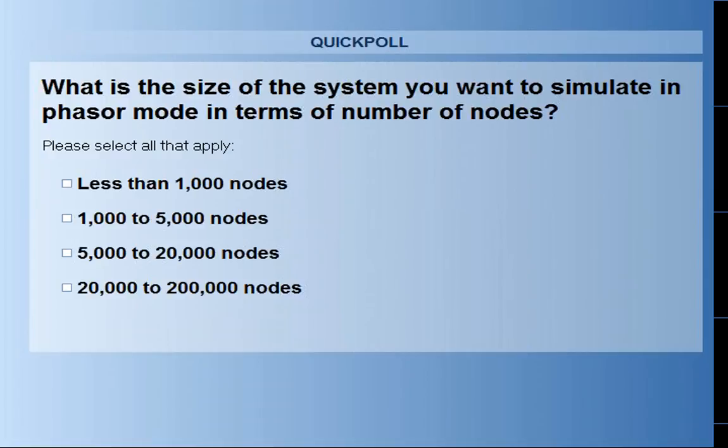If we zoom into that area, we can see several paths overloaded. And if you use the trend chart, you can also see there's a huge angle difference jump between the two areas, and the corresponding current also overshoots.